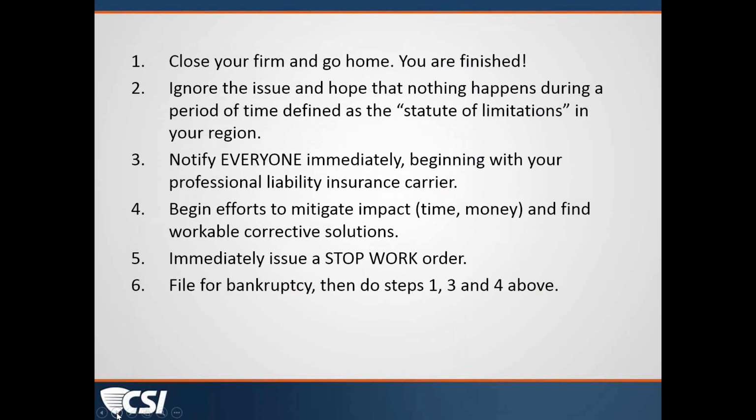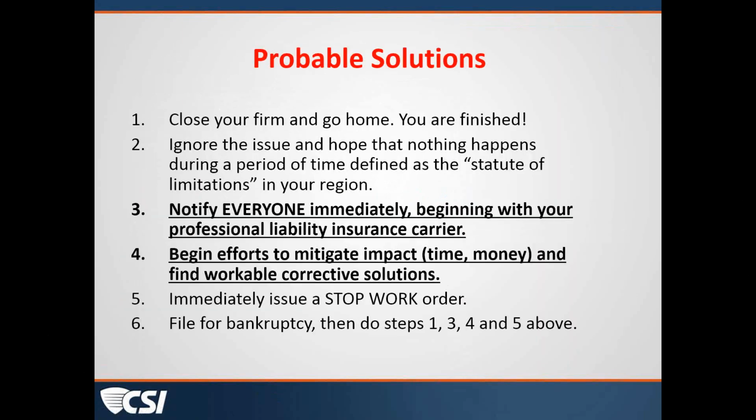There was one other additional comment pointed out that technically for number 5, unless it's an immediate safety issue, work stop orders typically would only come from the owner. I don't know if you wanted to talk about that at all. Absolutely. Doug, you want to field that? Well, that typically is a true statement. By contract, architects typically are not authorized to stop the work unless, as was mentioned, there is an imminent life safety issue. You could certainly recommend to the owner that the work be stopped and go to the contractor and maybe request it or recommend that it stop, but you are not authorized as the architect on the project to stop the work.